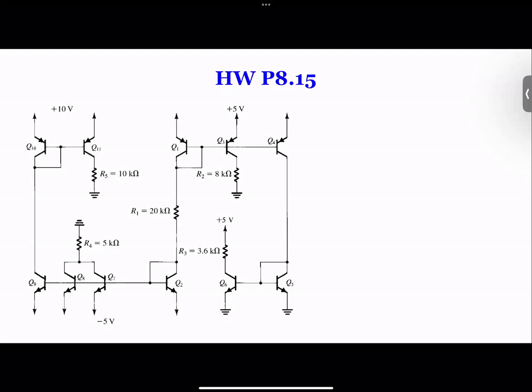And then we look at this one here. Oh, this is connected. Okay, and this base is connected. So everything here got to be a current steering circuit, another current steering circuit. And then apparently this is the reference one, and these are the results. And then look at the bottom here. Oh, this one is connected to the base. So therefore, this got to be like a current mirror type of device. And then this one is the result.